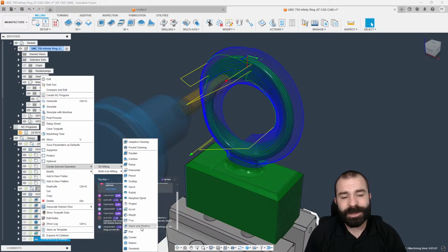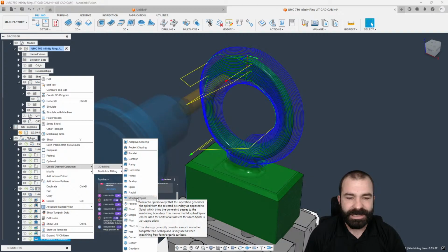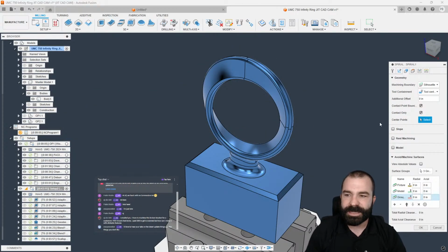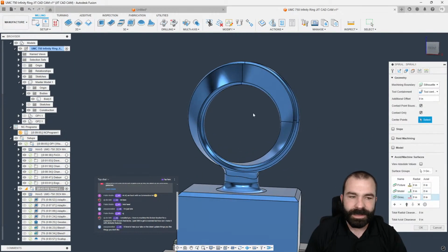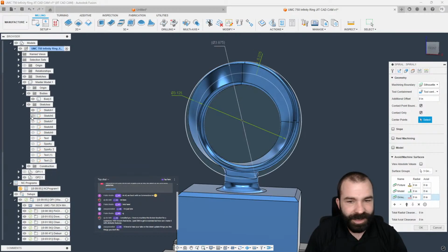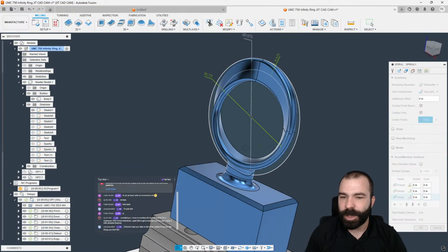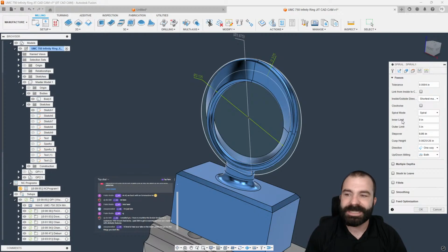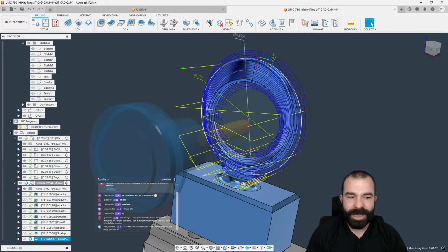So again, I don't necessarily know the end goal of the wants of the surface finish here, but as you guys can see, something like a spiral toolpath might be very beneficial. A few things about spiral you do need to know is we need to know a center point that we want to rotate around. Now, if there is a sketch in here, oh, telling, boom, there is a sketch in here. We could steal that sketch center point for our toolpath to go around from, right? Another couple of things a few people miss out on is there is an inner and outer limit as well to this toolpath. Usually you want to go ahead and set this outer limit quite dramatically bigger, but let's go ahead and see what that now does.